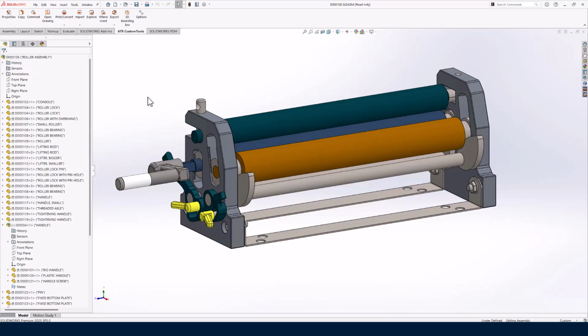Now I would like to do a bit more, because we can actually create at the end of all of that a PDF file that is merged, and then we can have that for review and see quite easily what needs to be done. Because obviously these drawings are not finalized in any way, but we can get a very quick result. We can have all the drawings created with predefined views, we can save them, and that is already quite a big task that we remove from our shoulders.